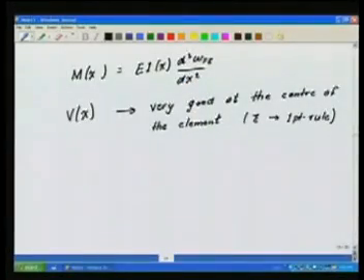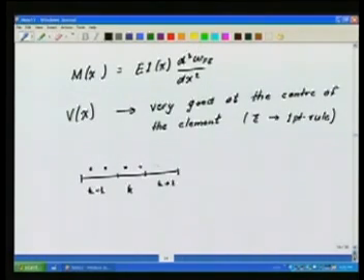Okay. Now there is another question: imagine that I would now like to get a good value of M of x or V of x, let us say M of x, at every point in the element. So again, what will I do? I have essentially the neighbors k minus 1, k plus 1. For the neighbors, I know that for each of the elements there are 2 points where the second derivative of w is good.